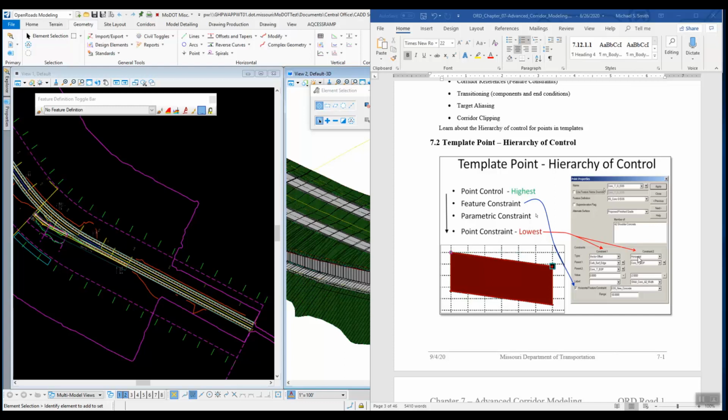So if you wanted to have the roadway go from 0+00 down to 1+00 and have it be 2 feet, then you wouldn't do any parametric constraint. And then if you wanted it from 1+00 to 5+00 to be 10 foot, then you would use that parametric constraint and override what's in this dialog. And that's a parametric constraint.